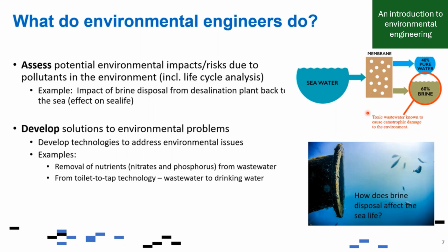So we need to provide additional source of water. Now the desalination plant in Sydney is working. But most desalination plants, what do they do? When you desalinate water, if this is seawater here, you use a membrane like reverse osmosis, and then you push that water inside the membrane, right? This membrane is a semi-permeable membrane. It means that it will only allow water to pass through, but not allow the salts to pass. So the salts remain on the other side.